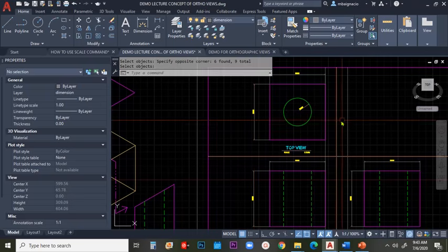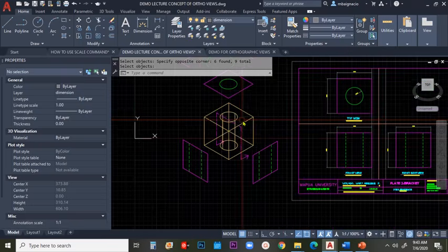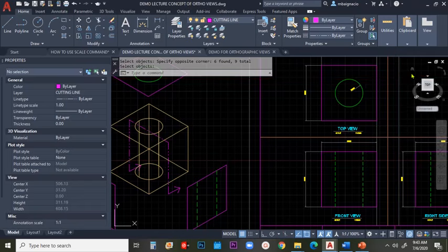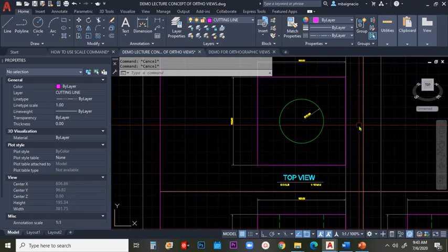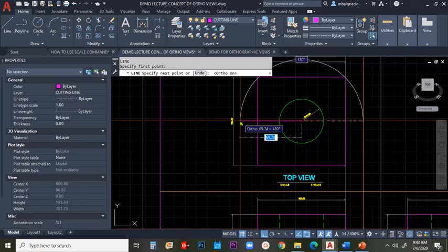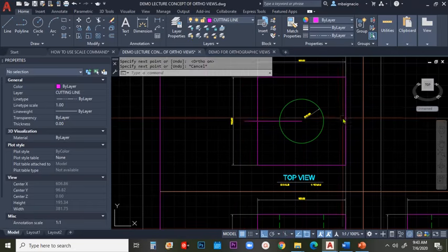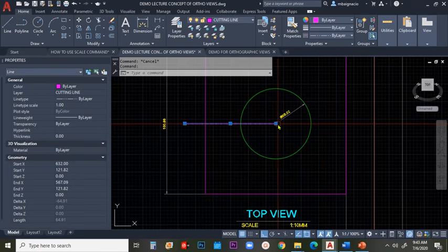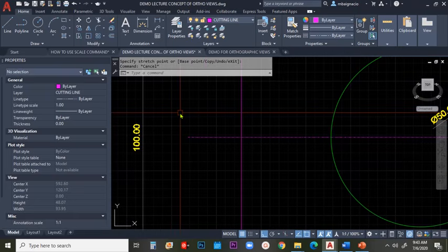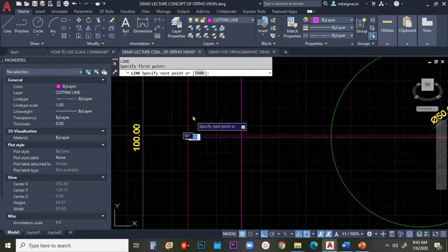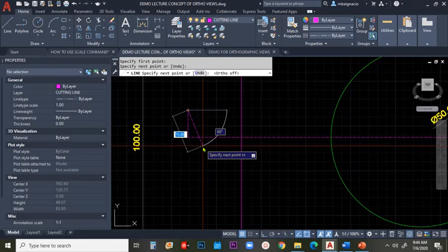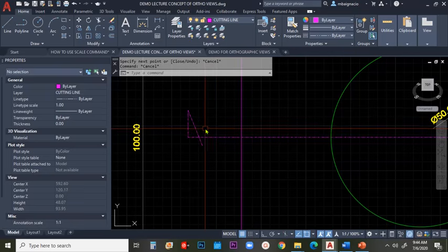From the reference class, you have a cutting line passing through center. So you turn on your cutting line, and then I want you to create a line passing through from the center. So create a line from here, center. Then be sure that F8 is turned on, and then extend it on this area. And then I want you to illustrate free draw, line, vertical, and a diagonal. Be sure that F8 is turned off when you create this.